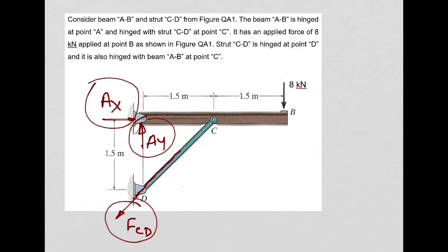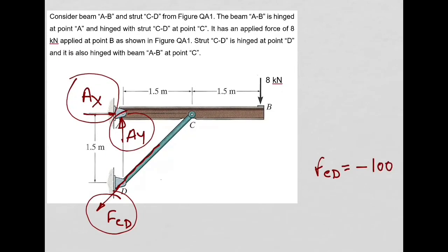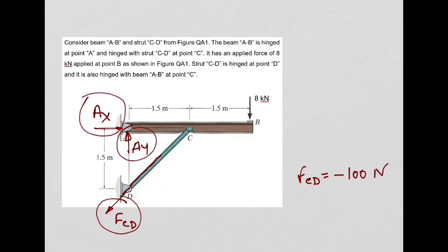Say, you worked it out and it was negative. You realised it was in the wrong direction. Is it still sufficient to give a negative answer because the diagram doesn't really matter? Well, if you just change the direction. Okay, imagine you get, for example, at the end, after solving the equilibrium equations, minus 100 newtons, right? You get this result for your force in the strut. And this was your initial assumption for the force FCD. So what you have to do is reverse this FCD. So your real force on the strut needs to be in this direction.